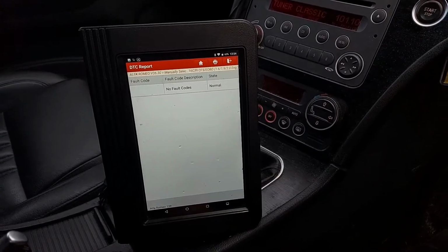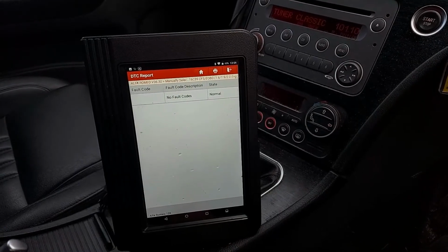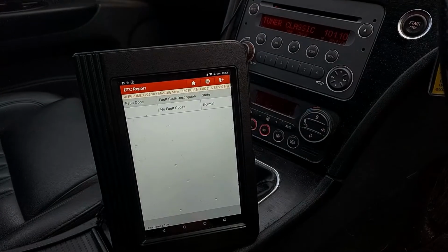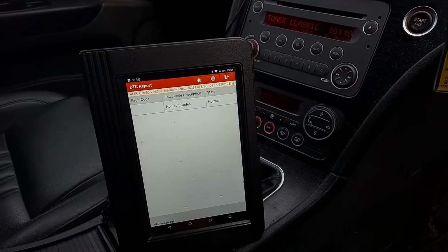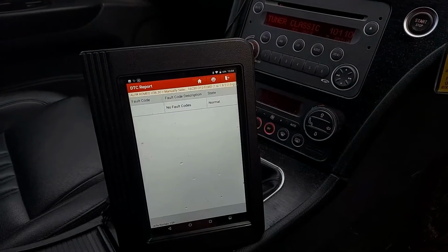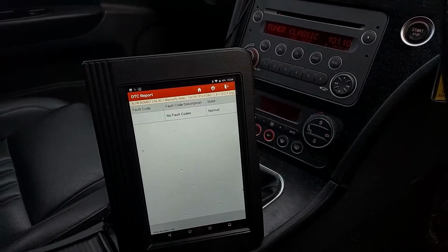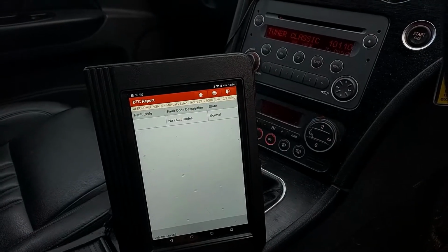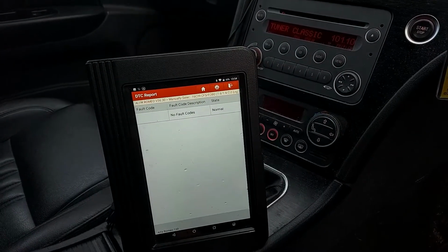So if you look at the wiring diagram, that fuse was powering up both the brake switch and the air mass flow sensor. So, big question now is, why did the fuse blow?